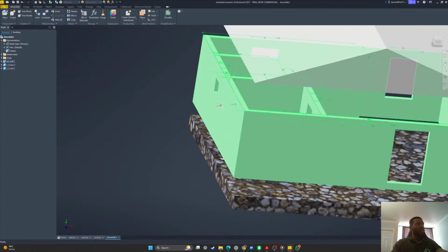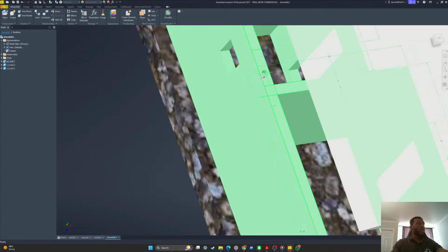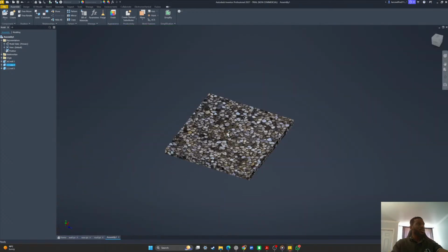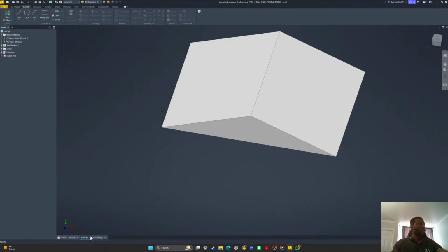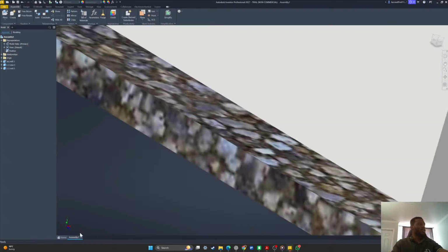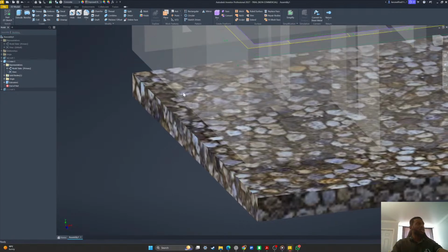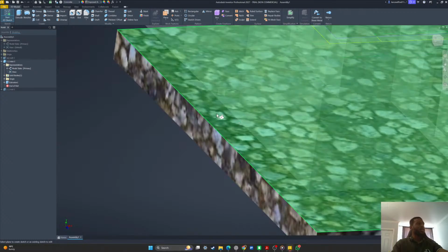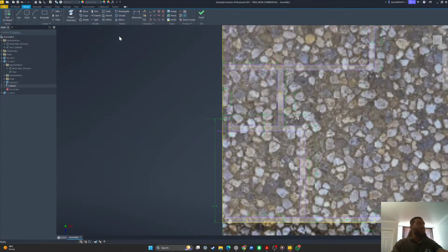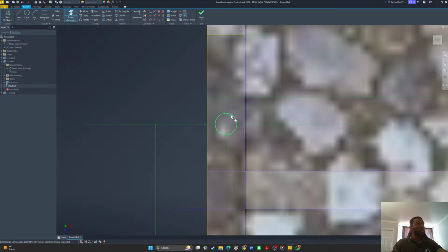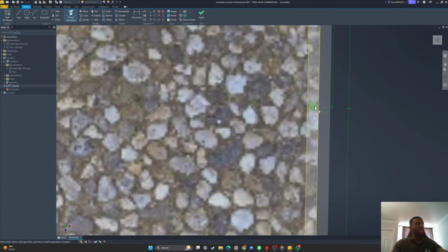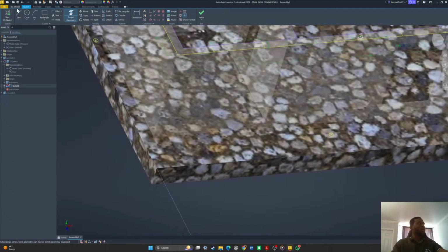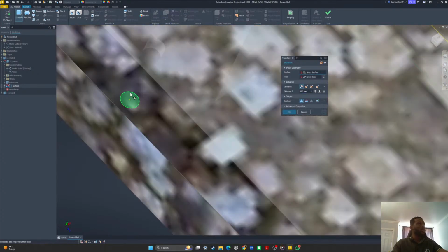So now all we have to do is make these holes. I want to make the slots where these are going to connect into this. So I'm going to close all of this. It's easier to edit this while you're inside the assembly. So now all I have to do is create a sketch. And then just like before, since we already have the position of the holes, all I have to do is project geometry, and right there. So now we know it's going to be in the exact position where we want it to be.